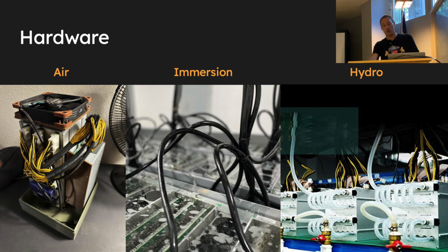And then you see hydro here on the right, which is much more specialized. It's a much more high-performing way of cooling just the areas you need to cool. So in this case, instead of all these fins and heat sinks that just add more surface area so you can reject that heat to convection, you have what's called a water block, and it's literally on top of all of the ASIC chips, and it has all these jets, and it's literally jetting fluid onto the chips. And this way you can use water, which is conductive if you don't demineralize it, but you get high convection coefficients because of the jetting, so just high velocity, you're throwing it at it.